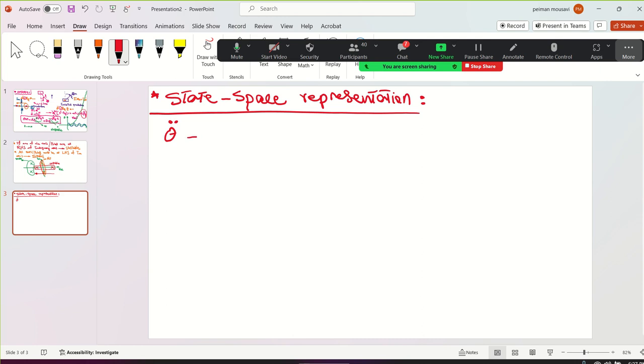So it's theta double dot plus omega n squared sine theta. Now we know what omega n is. I'm keeping it nonlinear now. Minus, now we have the moving pendulum, x double dot over L cosine theta. The state space means that, exactly as I'm doing, I'm going to copy this and write it in the code in MATLAB. Because at the end of this course, I'm going to use this example exactly to add the controller and show you how the control works, for this and for a robot.